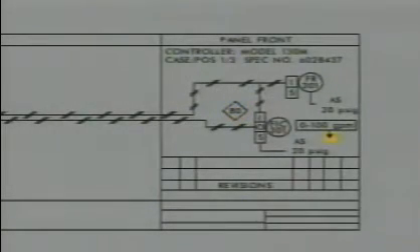Loop diagrams can also indicate how instruments respond to input signals. A controller action symbol, shown as a vertical arrow pointing either up or down, will be located near the symbol for the instrument or below the rectangle containing the flow range.